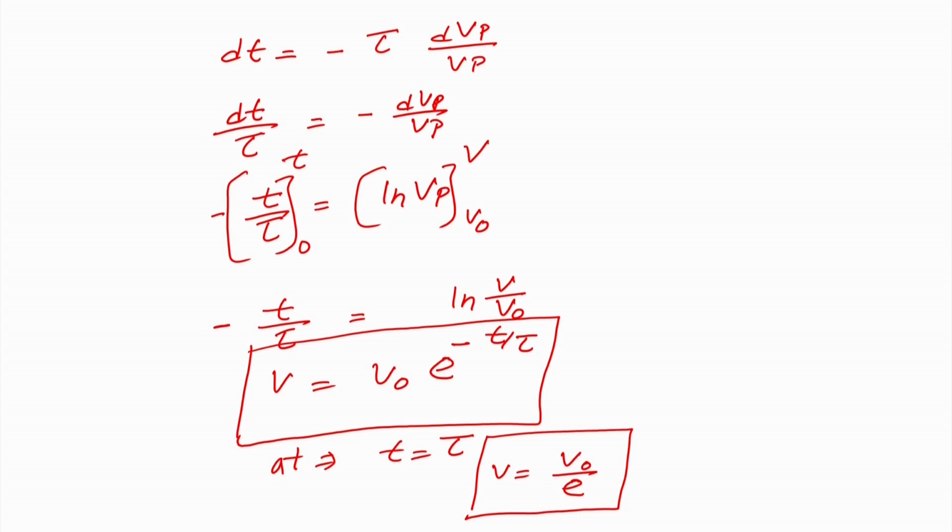So, you can find out the values of how the velocity will change with the time in case of the Stokes regime. Similarly, you can calculate the position, you can write the Vp as dx upon dt, and you can write the dt in terms of the dx, and you can calculate the x value, and again this is a very small thing, you can do the calculation, it will come as 1 minus e raised to the power minus t upon tau.